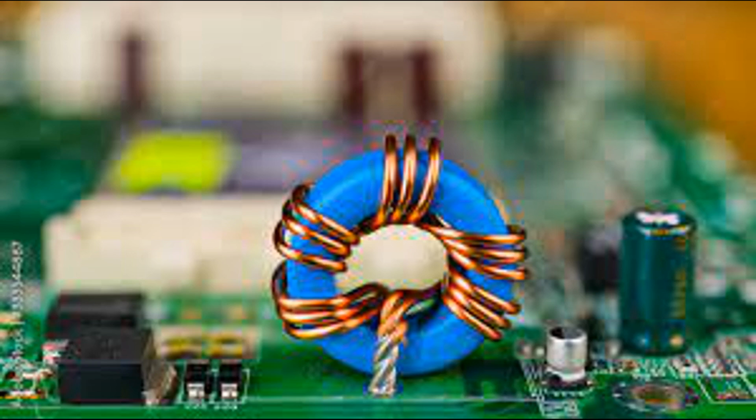Radio frequency, RF circuits. Application: choke inductors are used in RF circuits to block high-frequency signals that could interfere with the proper functioning of the circuit. They allow DC biasing while isolating different sections of the circuit from high-frequency noise. Example: in RF amplifiers, chokes are used to prevent RF signals from reaching power supply lines, where they could cause unwanted interference.